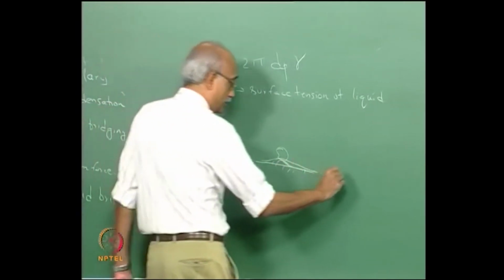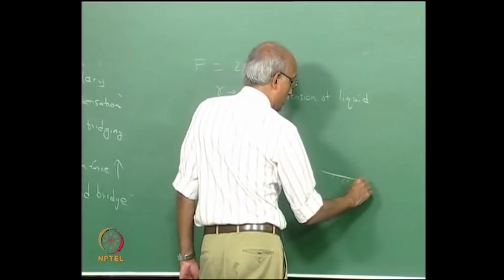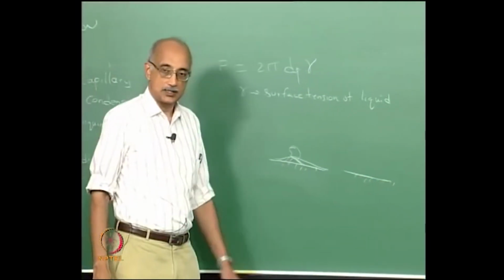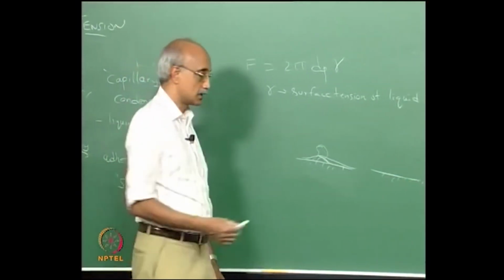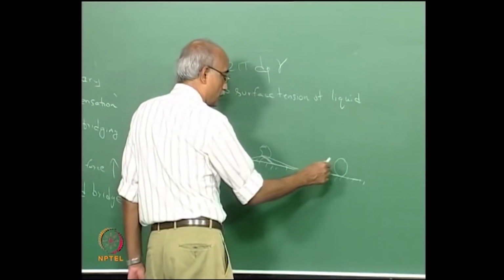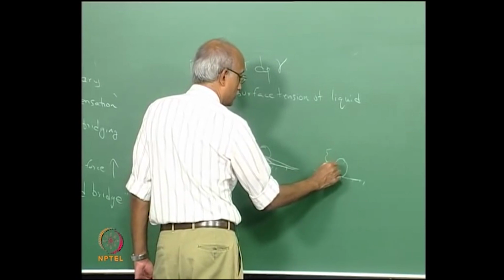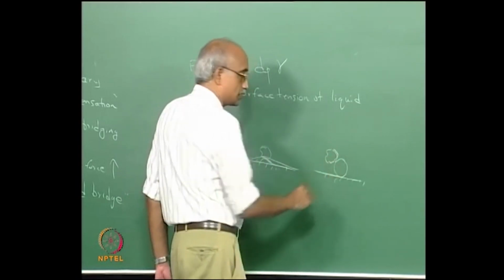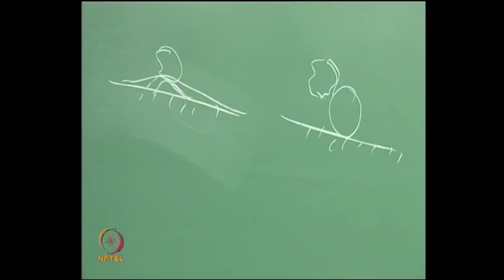On the other hand, if you have a surface and you have a liquid on it which has a high contact angle, something that tends to bead up like this, now the particle to surface adhesion force is definitely not going to be increased by the presence of the liquid. In fact, it could reduce the adhesion force.